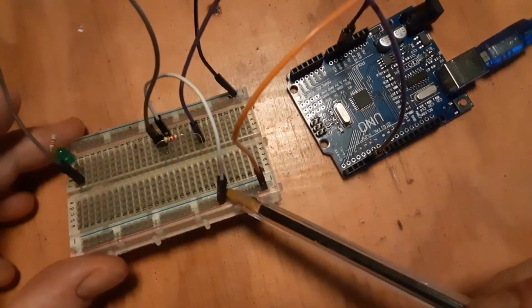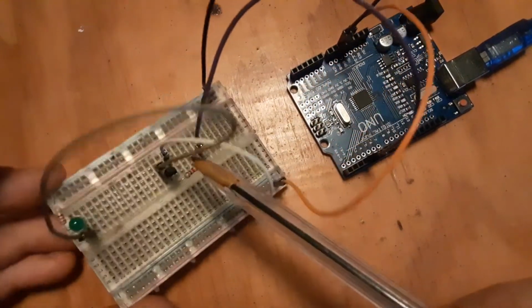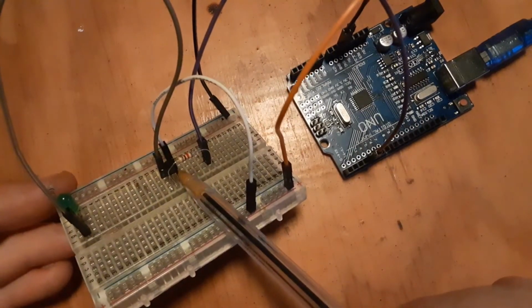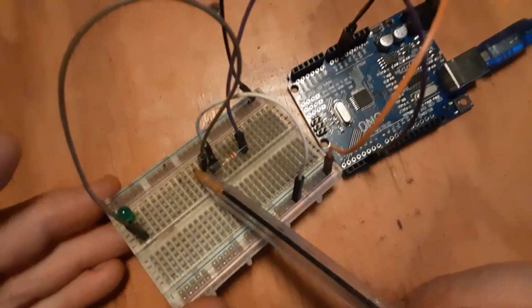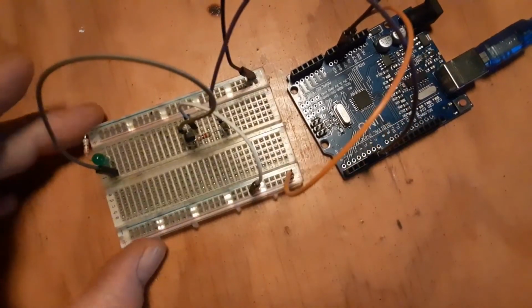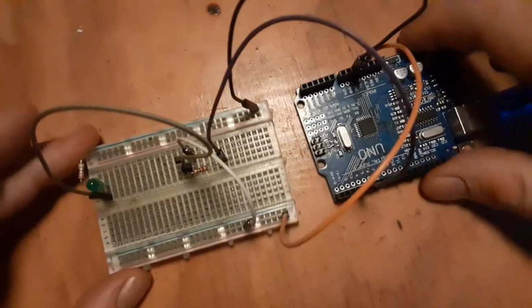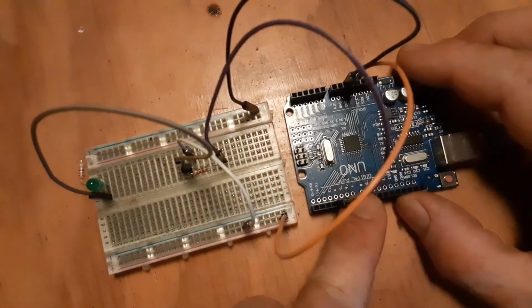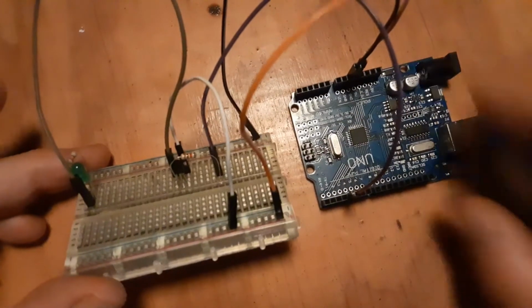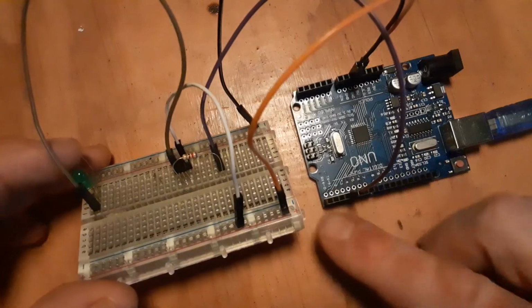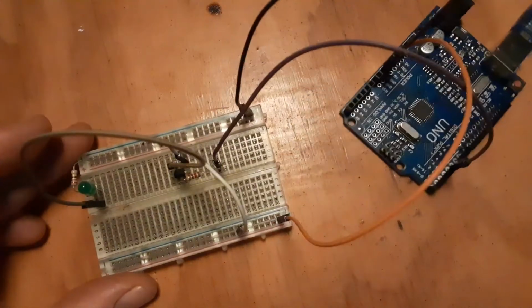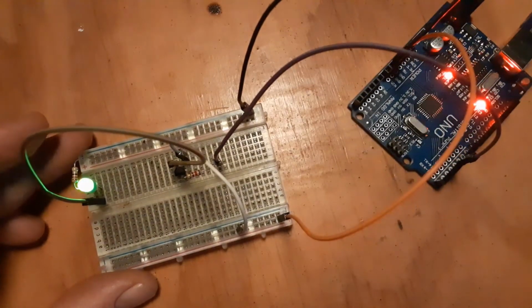And then the power is coming from this white line over to the emitter side of the transistor. And then the collector of the transistor is coming down this wire and powering an LED. So basically the Arduino would be enough, we could just power the LED right from the pin, but we'll get the same effect this way. Instead of going straight from the Arduino to the LED, our Arduino is just turning a switch on and off to express the point from today about switches.